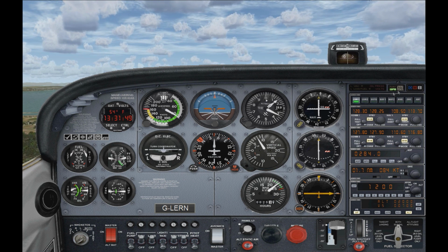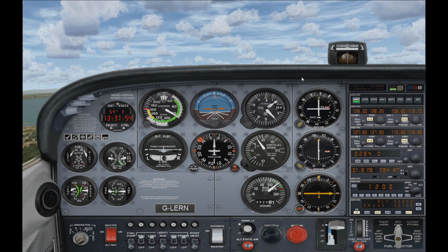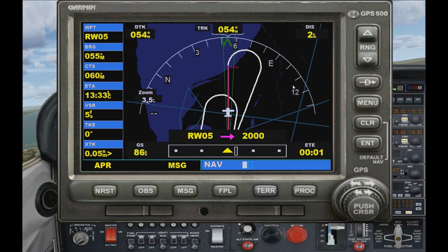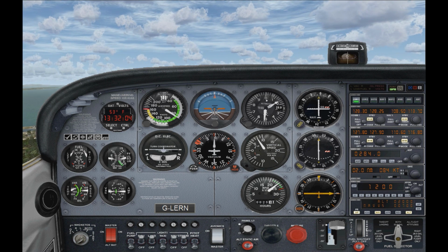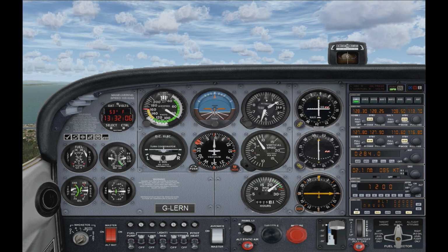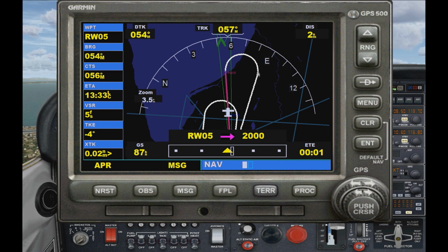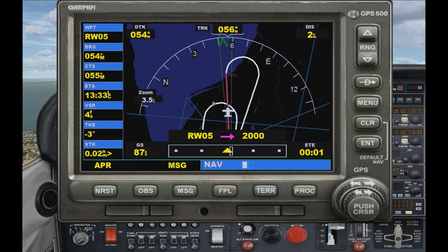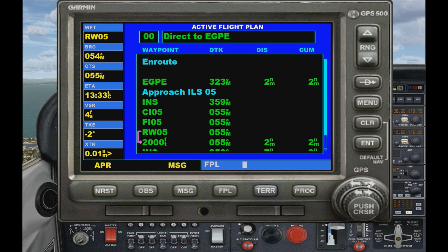And now that we've got GPS selected again, if we hit the nav switch, that will tell the plane to navigate onto that flight path there. And then there's not really much that's going to happen. All the plane is simply going to do is follow this line around back in towards the Inverness VOR, and then once it reaches the VOR again, it will automatically jump onto this holding pattern, and I can show you that just now if I do that.